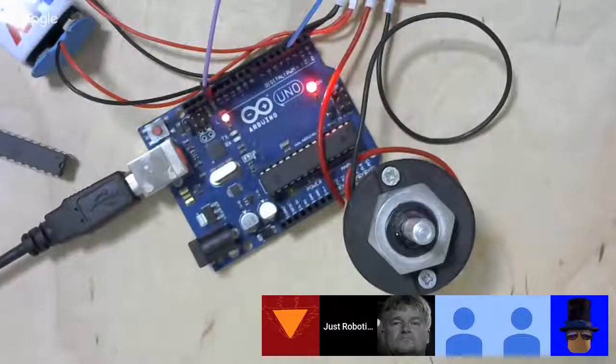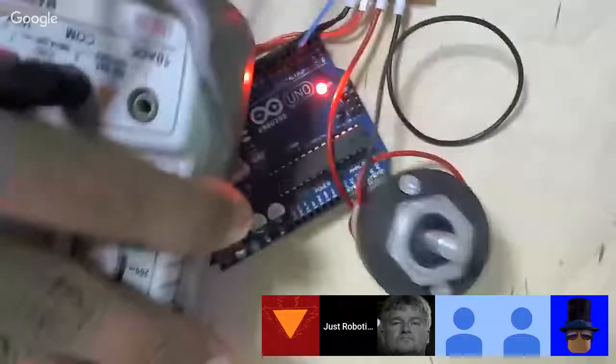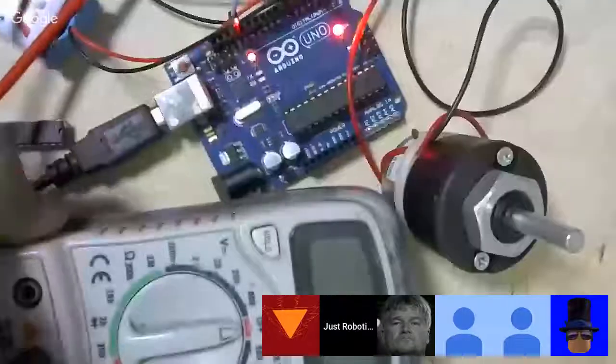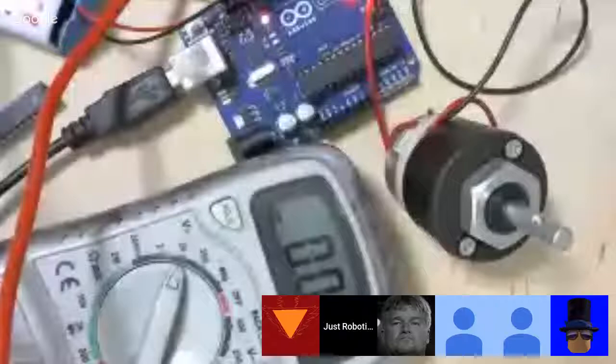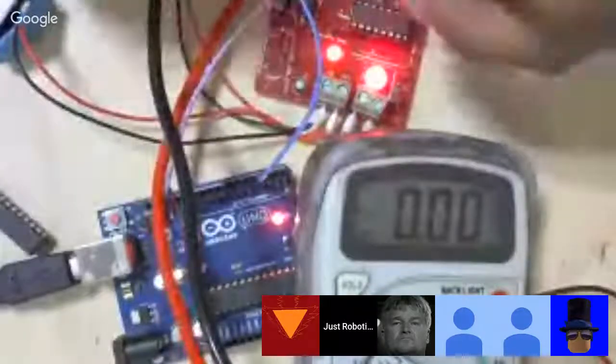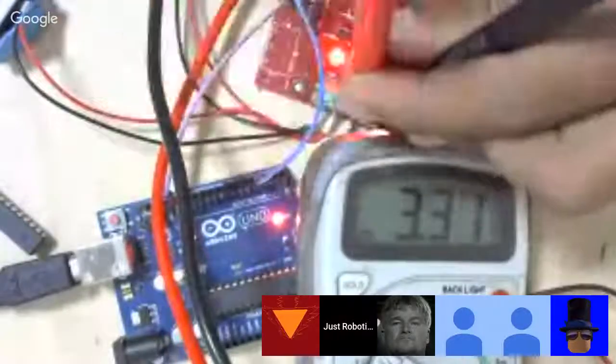Right now I've kept it at 127, and let's see what is the voltage that comes to the output pin. You see the multimeter here. Just turn on the multimeter. Okay. I just push this out. Bring the multimeter back in the screen. And then let me check what is the voltage that I'm getting when I connect it to this. So you'll see that it's about 3.3 volts.